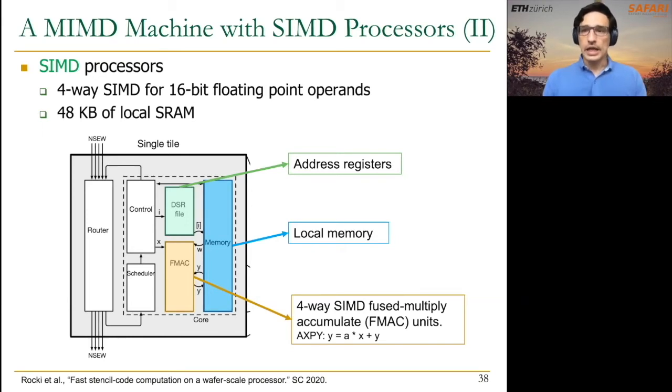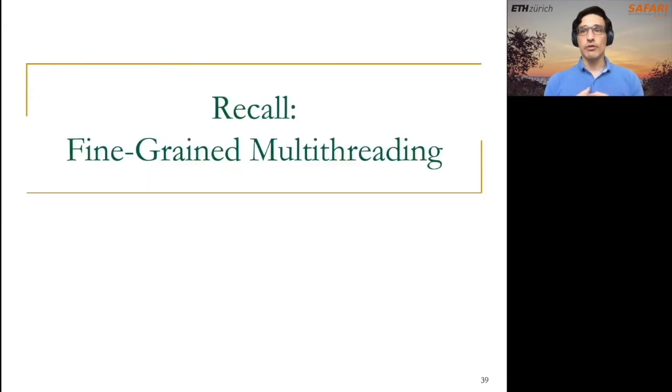Okay, so until now, this is our SIMD processors lecture. Now we're going to start talking about GPUs. But before we start talking about GPUs, I would like to remind you of the fine-grained multi-threading paradigm, or fine-grained multi-threading execution, because GPUs, as you already know, are related to SIMD processors, but they also have the ability to execute SIMD operations in a fine-grained multi-threaded manner.